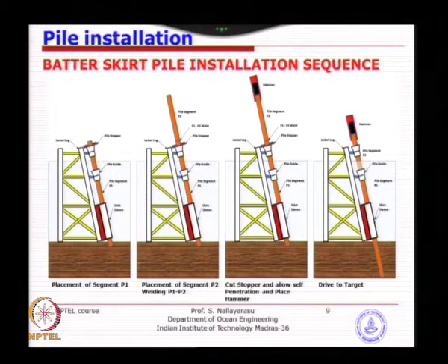The one great advantage of this is that the pile is always laterally supported here, and here, and also supported here. So the length of the unsupported section is limited. Your slenderness ratio will be lower, and the design stresses will be lower.